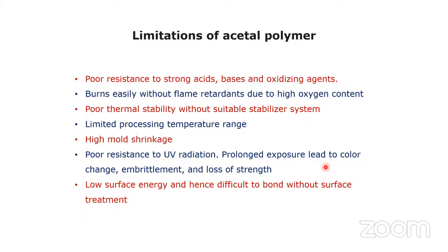In a similar way, if there is continuous oxygen in your polymeric chain, it tends to burn. It's not that it will directly burn, but in the presence of a flame, it will start burning. That's why in many polyacetal materials, flame retardant additives or fillers are added, due to the presence of oxygen moiety in the polymeric structure. It also has poor thermal stability without a suitable stabilizer system. If you have a thermal stabilizer system, it will show its thermal properties.